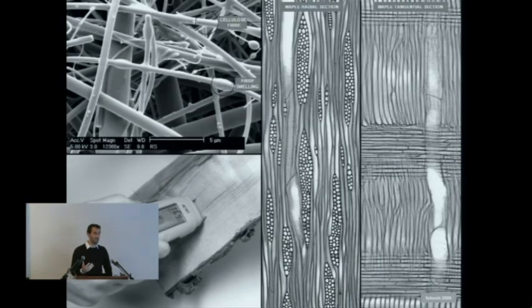So as probably some of you know, wood is a hygroscopic material, which means it maintains its moisture content in equilibrium with the surrounding relative humidity. So the related processes of adsorbing and desorbing water molecules affect the microfibrillar structure, resulting both in a change of strength and a differential change of dimension.